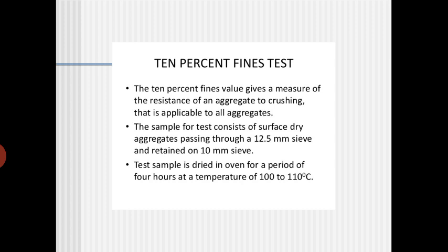Then this kind of aggregate is subjected to a compressive load. Normally in this we will use one cylinder. In that cylinder we will apply the aggregate layer by layer, normally 3 layers. Then we will apply a compressive load on those 3 layers.